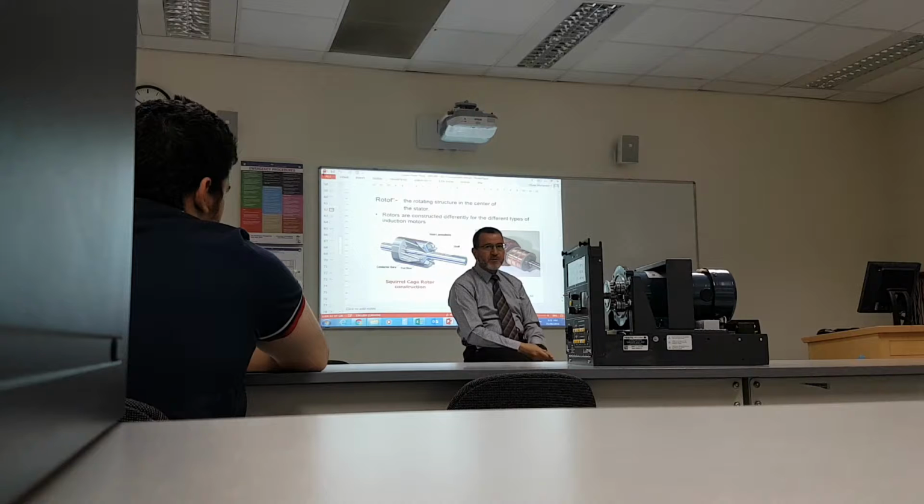And these types of motors that are used as capacitors, they don't even have any connections to any external load. They just run like that. It's just a motor for power factor correction. Of course, capacitors are simpler, right? Capacitors are not as adaptable to changing loads. A motor is. By adjusting the excitation, you can change how much power factor correction you want to introduce in the system.